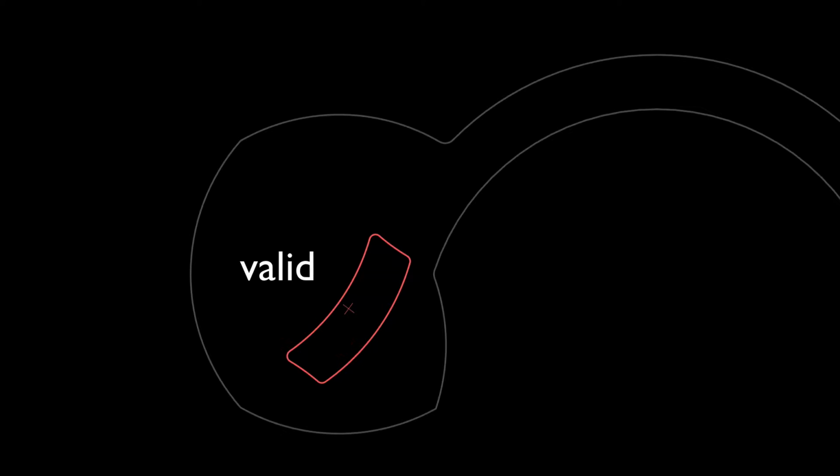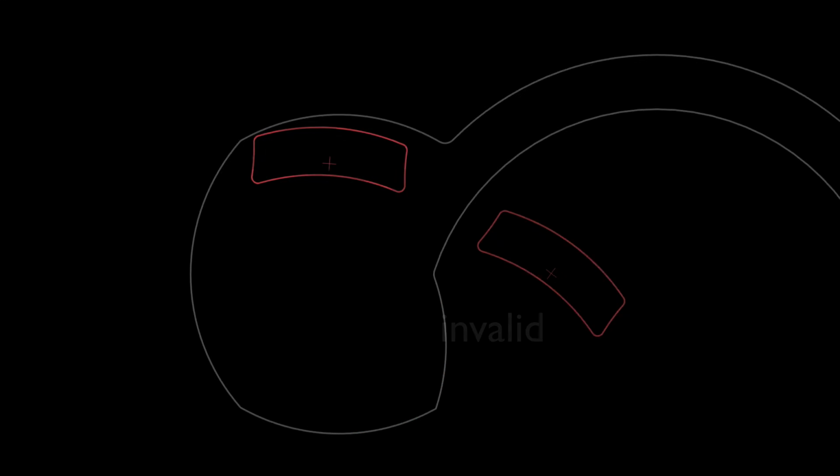We are interested in visualizing the valid placements of the robot. For a fixed orientation, this free space is the set of translations such that the robot does not overlap the obstacle. It is bounded by arcs called subedges, also parameterized by alpha, that exist where a robot and obstacle edge make contact. The subedges are shown in green.